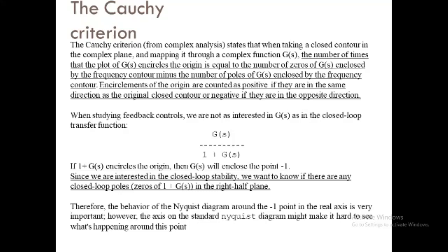This Nyquist diagram is basically a plot of G(jω), where G(s) is the open loop transfer function and ω is a vector of frequencies which encloses the entire right half plane. While drawing the Nyquist diagram, both positive and negative frequencies from 0 to infinity are taken into account. In the illustration, we represent the positive frequencies in red and the negative frequencies in green.